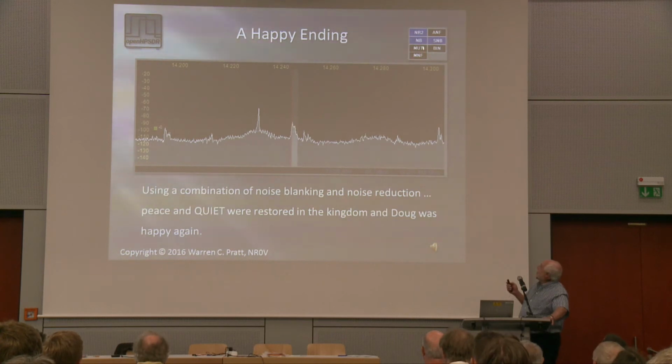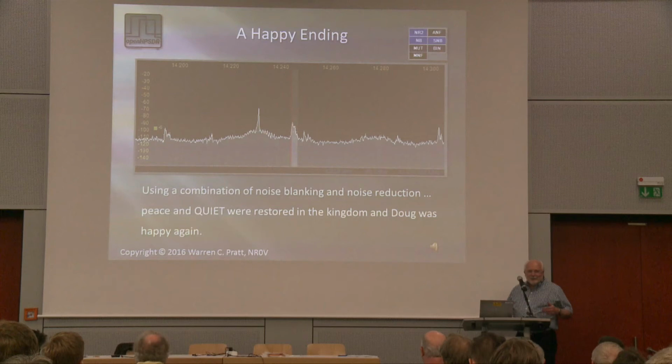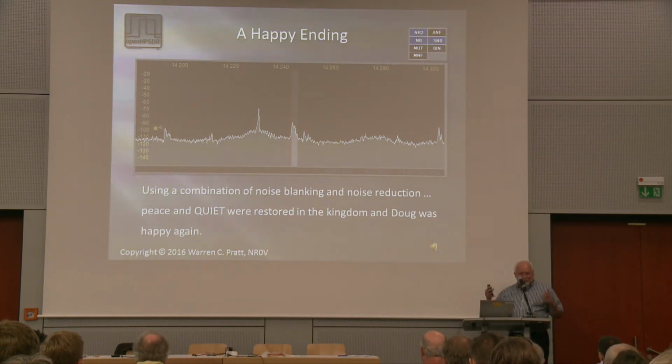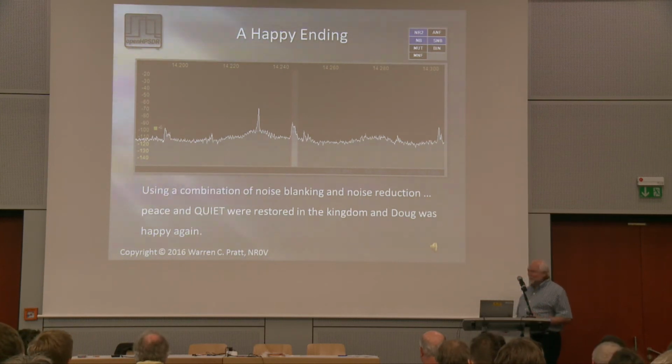Well, we've turned on a wideband blanker, our spectral blanker, our spectral noise reduction. Pan adapter looks a lot better. It's down about 25 dB. We're seeing some signals on the band now, so that's encouraging. But the real test is, what does the audio sound like? And even though the voice said that it's a happy ending, I think you're going to have to decide if it's a happy ending. So let's listen to what we hear with those tools turned on.